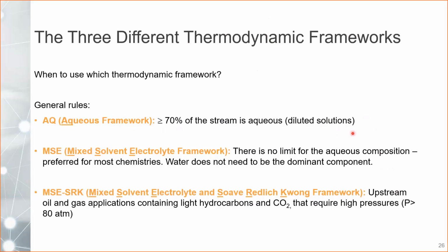Okay. Then if you have the mixed solvent electrolyte, this one is very useful when you have a solvent that is different than water. Okay. So you have your solvent is sulfuric acid or methanol or ethanol, any other solvent that is not water. This mixed solvent electrolyte works beautifully for those systems. Or when water is present, but water is not the dominant component. So that one can also be used for those specific scenarios.